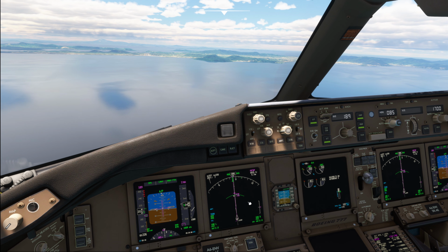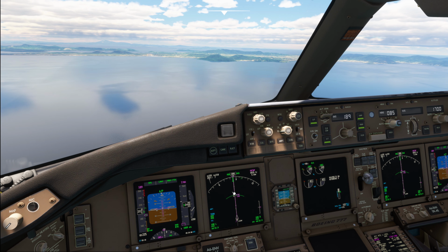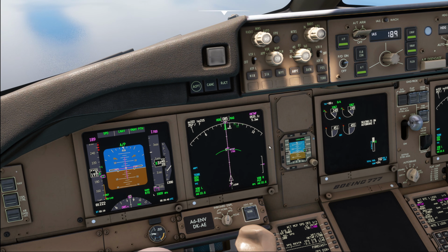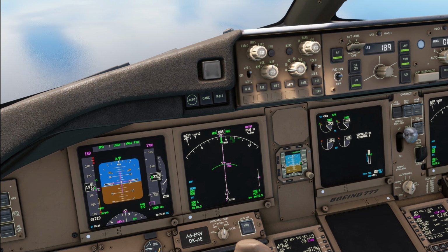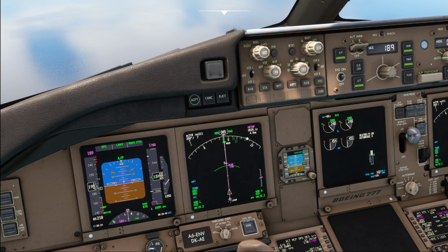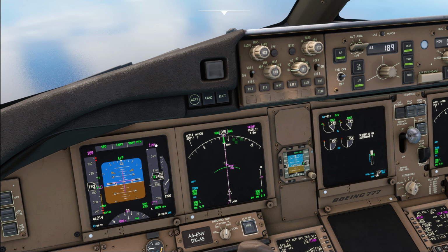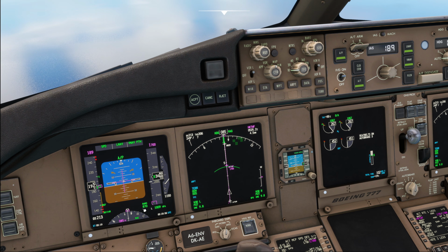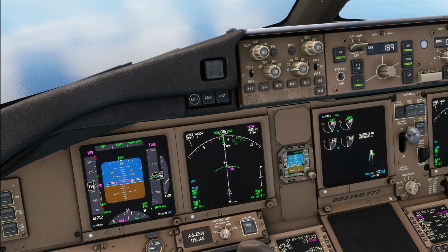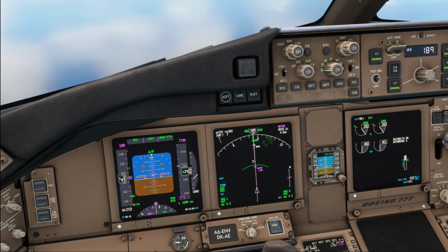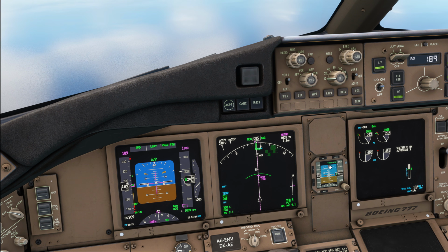Alright, so we now have 1700 feet at our final approach fix. Things are going to get hectic once we're approaching that. So let's just revise what we are going to do next. 2 miles prior to the final approach fix, we're going to set our altitude down to our minimum, that's 870, and as soon as we are at least 300 feet below our missed approach altitude, so missed approach altitude 4,000 feet today, in other words, we basically are going to be below that straight away.